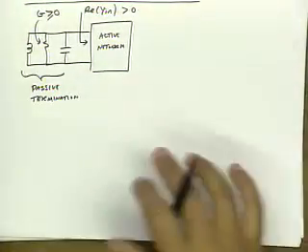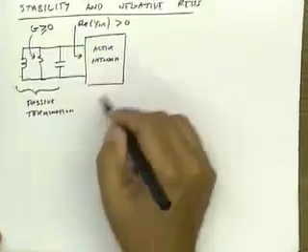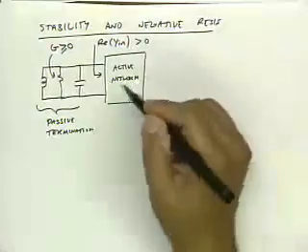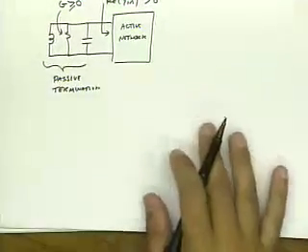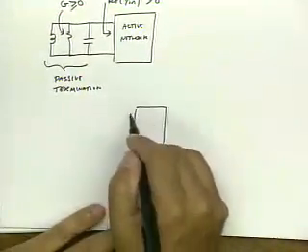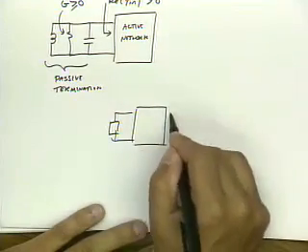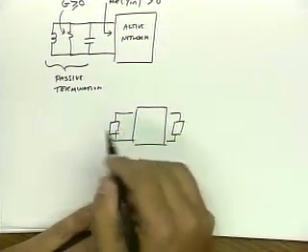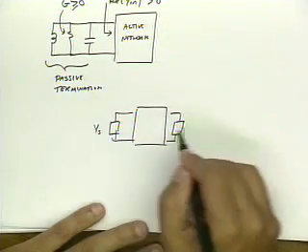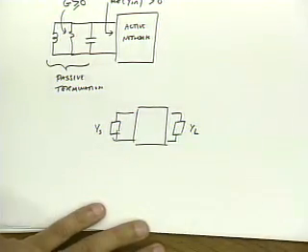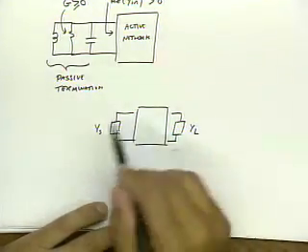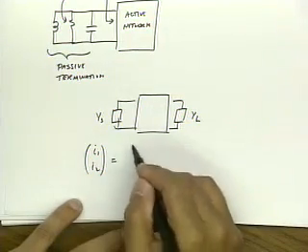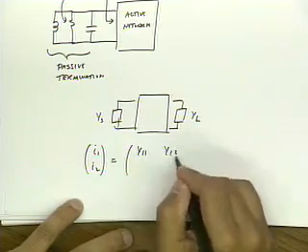All right. So let's look at this problem. So this is a one port, and it's actually quite trivial. I won't even prove it because it's so trivial for one port. So let's see what happens for a two port. So same condition on a two port. We want to terminate input port and output port into a passive load. So again, we call this YS and YL, and we want nothing to happen with this circuit. Well, we know that this circuit is described by the Y parameters.